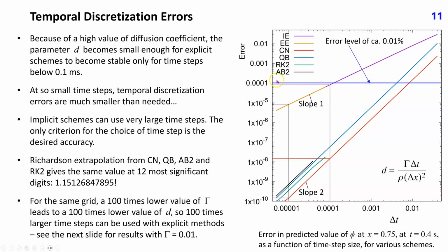If the aim is to have errors around 0.1%, this can be achieved with implicit second-order schemes with time steps which are 2 orders of magnitude larger than the stability limit of explicit methods. Explicit methods are thus not suitable for problems dominated by diffusion, especially if small grid spacing is required, for example, to resolve the boundary layer at walls, because of this dependence on grid spacing.